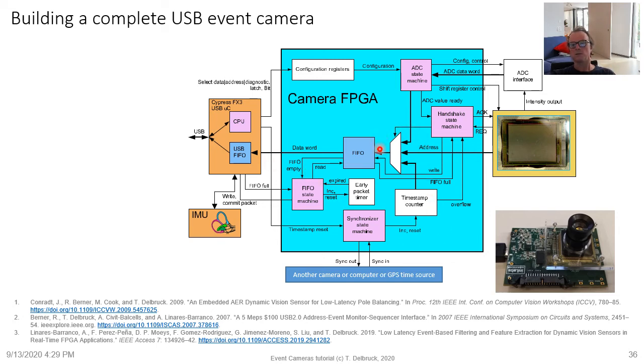So all these things are multiplexed together, and these purple state machines here then all interact in order to orchestrate the data using different flags like write and FIFO full to get the data into a FIFO. So this is another memory FIFO that Rafa, I think, first implemented, and then Luca Longinati at Inilabs and then Inivation greatly improved on this whole framework. I'm sure other startups have done the same thing.